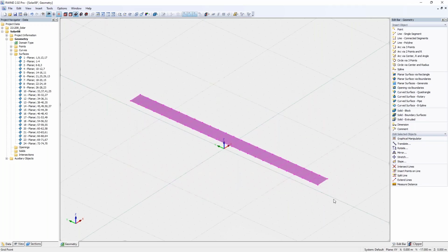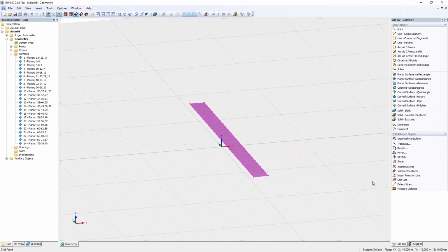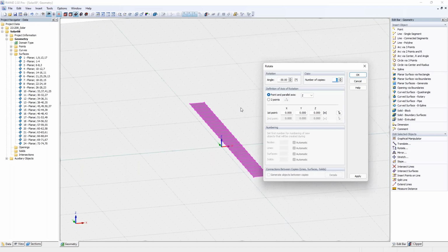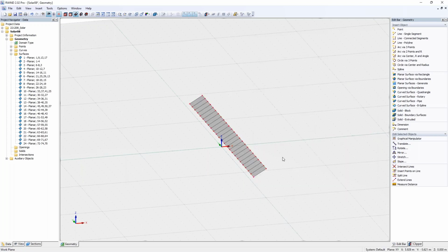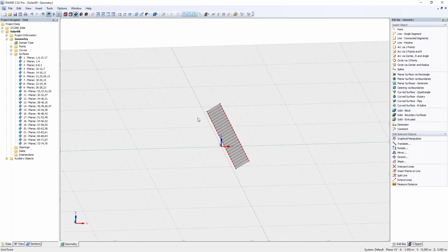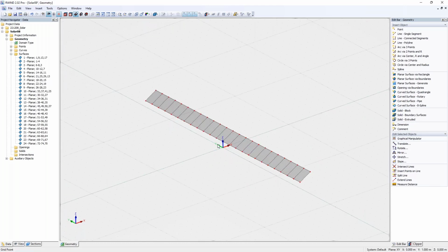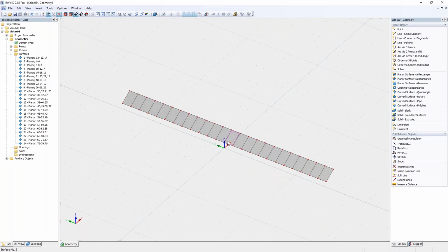And then I want to rotate them a bit because usually they are not laying horizontal. So I'm marking everything, hit the rotate button, and I want to have it minus 30 degrees, no copy. It's the y-axis. So of course I want to rotate them into the wind direction. And since I moved them already, I have to pick at least my node in here. It's also available only for Z, and then they will be put in a 30-degree angle into the wind. It might also, of course, be not 30 degrees. Then you might now save this model, put it back, and create another model with 20 degrees if you want to do some parametric studies for your file.